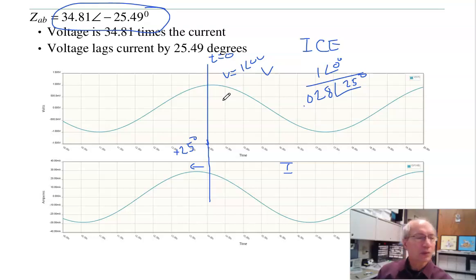Up until now, we've been using multimeters in lab. For DC analysis, I just need a number. It's 2.7 volts. For AC analysis, I need more information. That's an oscilloscope. For AC and oscilloscopes, I can sit there and look at the waveform. That's what oscilloscopes do. They give you a picture of what the waveform looks like versus time.